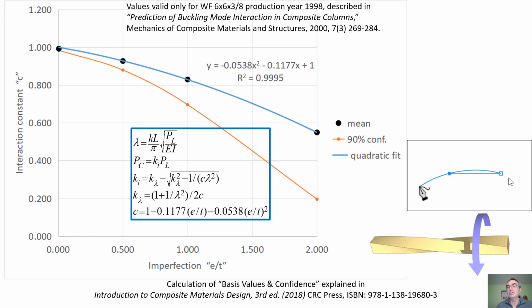It has a little bit of curvature, and if you know that value, then you can calculate an imperfection. And the other thing is, you think that the cross-section is perfectly aligned, there is no twist, but really there is a little bit of twist. If there is a little bit of twist, that number, the twist per unit length or something like that, will be given, hopefully, by the manufacturer, and if it's not, you demand that they give it to you. And with that, you can calculate an imperfection.